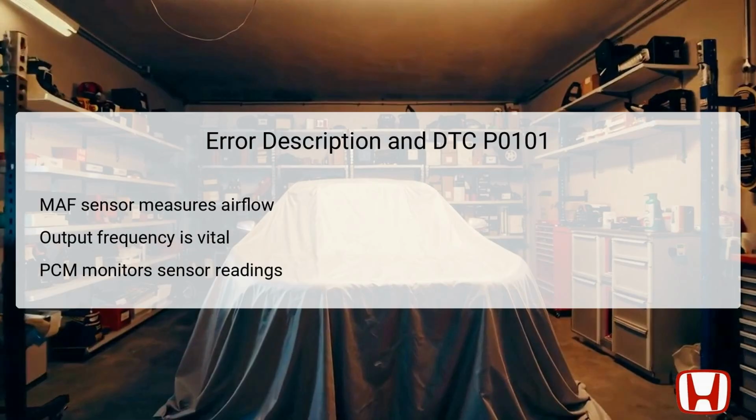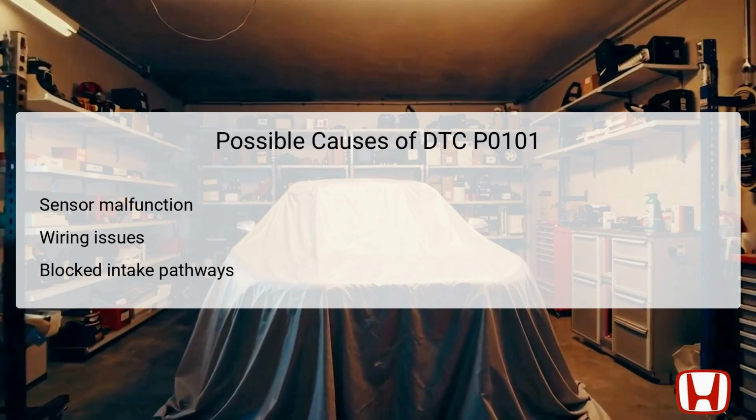Understanding the role of the MAF sensor and its placement within the air intake system helps in effectively diagnosing and troubleshooting this DTC. Several potential causes could lead to the triggering of DTC P0101, each affecting the MAF sensor's ability to provide accurate information. First, a malfunction or failure of the MAF sensor itself could distort its output frequency, leading to erroneous readings. Second, any wiring issues, such as frayed wires, poor connections, or corroded terminals, can prevent the sensor from functioning correctly or providing accurate data to the PCM.